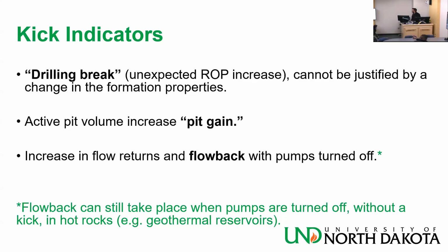So in that case, if you are drilling as a driller, you know very well that the deeper you go, the higher the temperature and pressures, depending on the formation. So how are you going to cater for the mud to contain a higher temperature and high pressure formation? You have to put the right additives in the mud, and make sure that your mud can withstand these higher temperatures. Not just the mud, also the tubulars, the bit, the MWD tools, everything in the BHA must be able to withstand those temperatures.